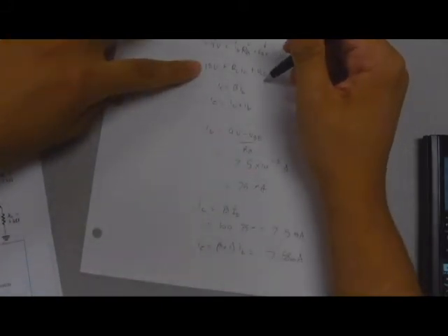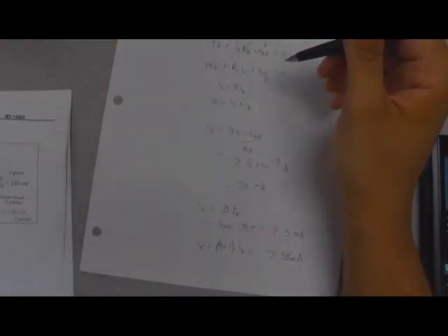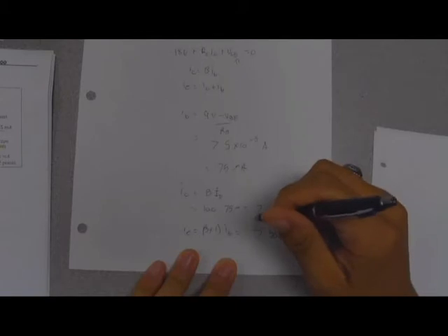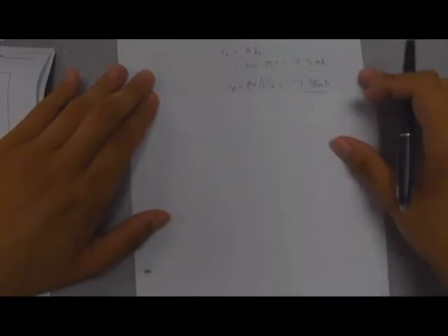Okay. So we're going to look at now calculating what this VCE value is. So now that we have IC and IE, we can continue to analyze this problem. But one thing to take note of is that we're dealing with a real source here. So if we look back at our network, we have this 18-volt source and this RC. So what's the maximum current that can flow through this circuit?